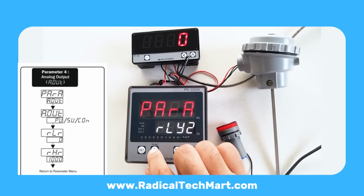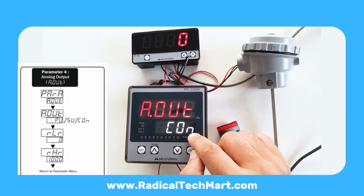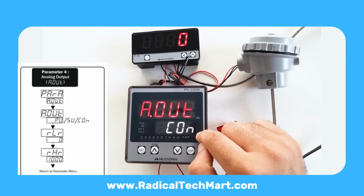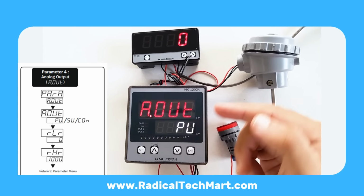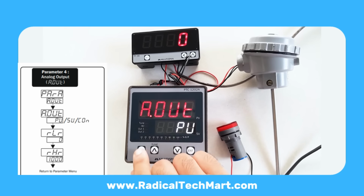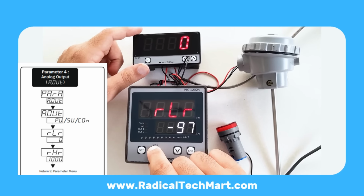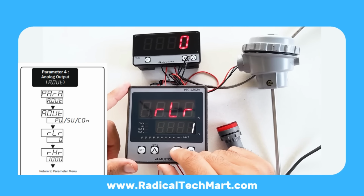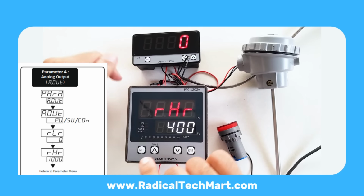Go to AOut, analog output. Control: the AO is your PID control output. On the display, a quick tap on set shows CSET, analog control set point. Raise CSET above PV and you'll see the bar graph rise, more output. PV retransmission: AO meters the present value. Set low range to 0 and high range to 400. Example: your remote indicator, Pi38, should be scaled to the same. You'll see PV match on both devices.